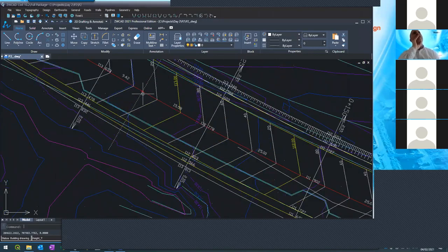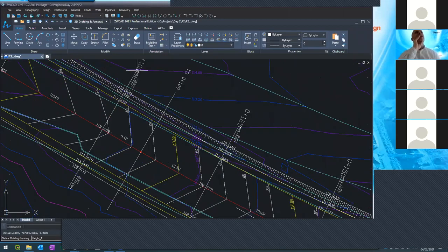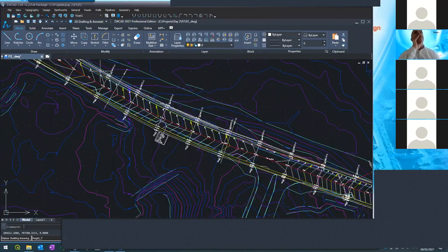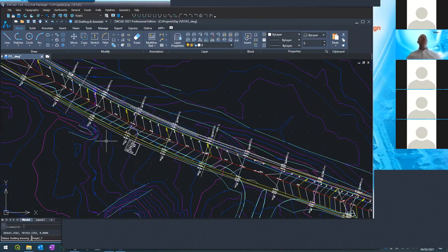I want to take it and add 1.5 meters wider, these two lanes on the right, when I enter the curves. Actually, I want to start it from this section, 0+100, and end up in 0+225. So from 0+100 to 0+225, I want the right side to be wider by 1.5 meters. Let me go to the cross sections.